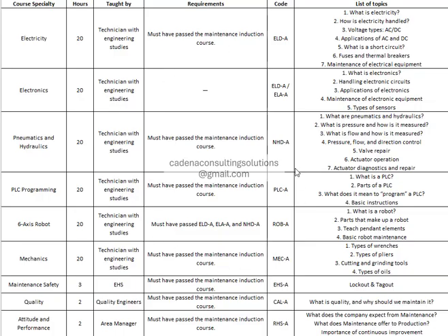This complete structure is only a reference. More detailed and specialized content should be developed based on the company type and equipment use. For example, many automation components such as valves that work well in a battery manufacturing facility might not be suitable for a high-pressure die casting environment, where valves can get stuck due to the heavy, dirty, and debris.